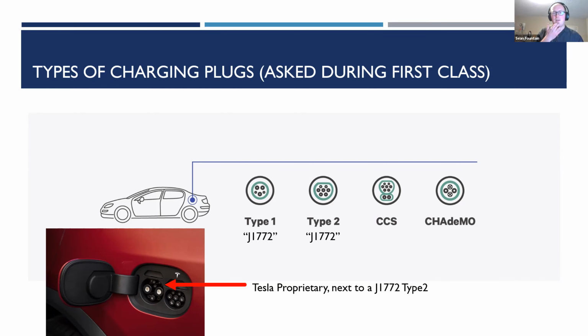But the landowner can pay $15,000 to $40,000 to put in one fast charger, and that doesn't even account for often having to upgrade the grid connection. For the 220 volt plugs, assuming they don't have to dig up an entire parking lot, it may cost $2,000 to $5,000 per plug, mostly permits and having to trench and add wires. The actual box itself is about $500.